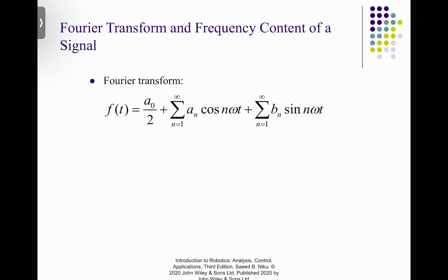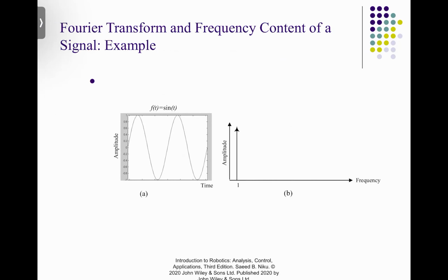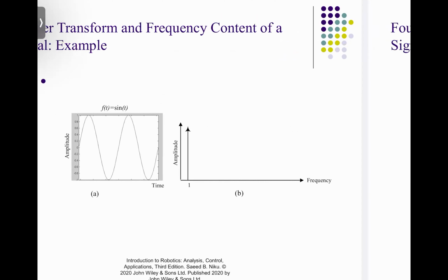We looked at the Fourier transform. Fourier series is a technique wherein you have a periodic signal, we decompose it into its subcomponents and then use signal processing techniques to extract the information from that signal. We also talked about the Fourier transform, which is nothing but the Fourier series when the limits are stretched to minus infinity to plus infinity, which means for a non-periodic signal or a periodic signal, you can use the Fourier transform to analyze.